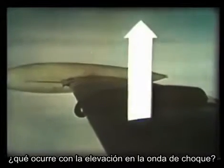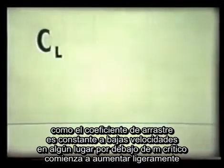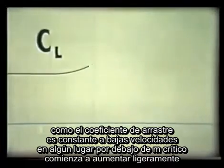So much for drag. What happens to lift of the shock stall? It drops suddenly. Again, watch the behavior of the lift coefficient. Like the drag coefficient, it's constant at low speeds. Somewhere below M crit, it starts to increase slightly.